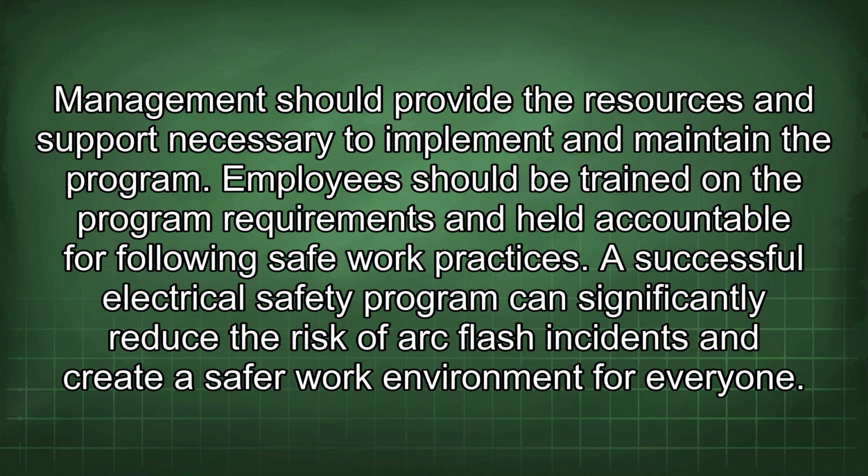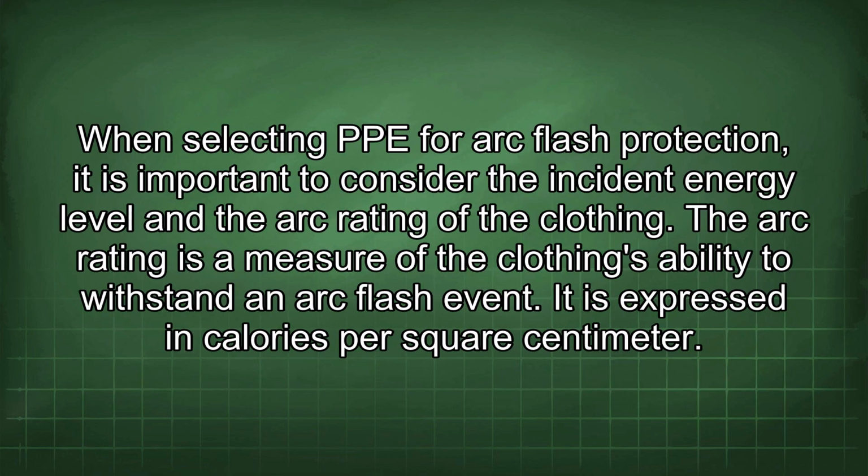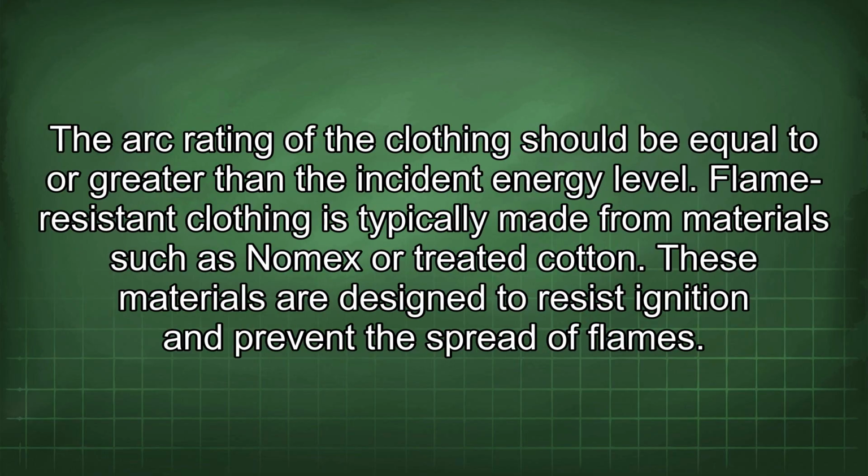When selecting PPE for arc flash protection, it is important to consider the incident energy level and the arc rating of the clothing. The arc rating is a measure of the clothing's ability to withstand an arc flash event. It is expressed in calories per square centimeter. The arc rating of the clothing should be equal to or greater than the incident energy level.